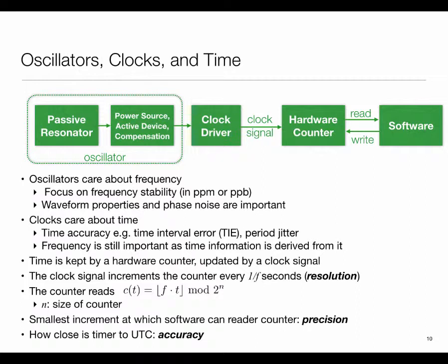can keep changing because my oscillator may be unstable. So even if I were to precisely set that offset to 0, which in itself is impossible to do, generally speaking, but let's say we were to do it, then after some time that gap will change, because again I'm comparing against the reference. Humanity has defined an average of some 300 atomic clocks as our agreed-upon notion of what a stable oscillation is, and our oscillator is going to keep shifting from that. And the oscillators you find in devices can be pretty bad. I mean, tens of ppm or even some 100 ppm.